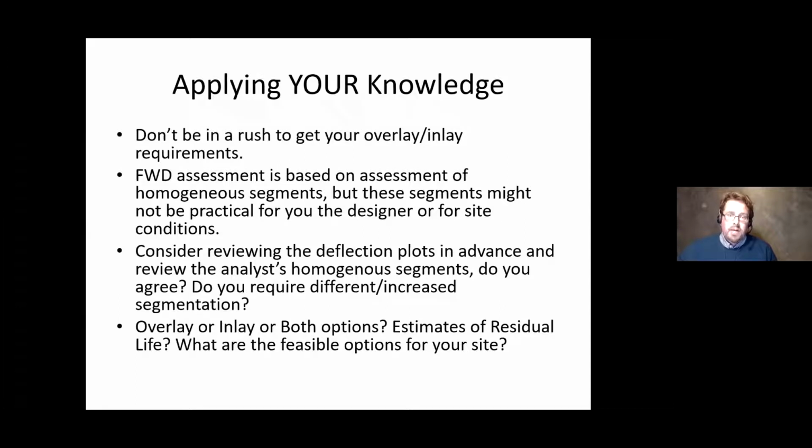It shouldn't be a matter of just waiting for the report. Engage with them while you're doing the work. And do you need an overlay or an inlay or both? It's becoming more and more common that an inlay will be required. You will need to remove the surfacing so that you get a proper bond. And in terms of recycling material, people are much more conscious about not burying good stone under good stone. So could an inlay be the option?